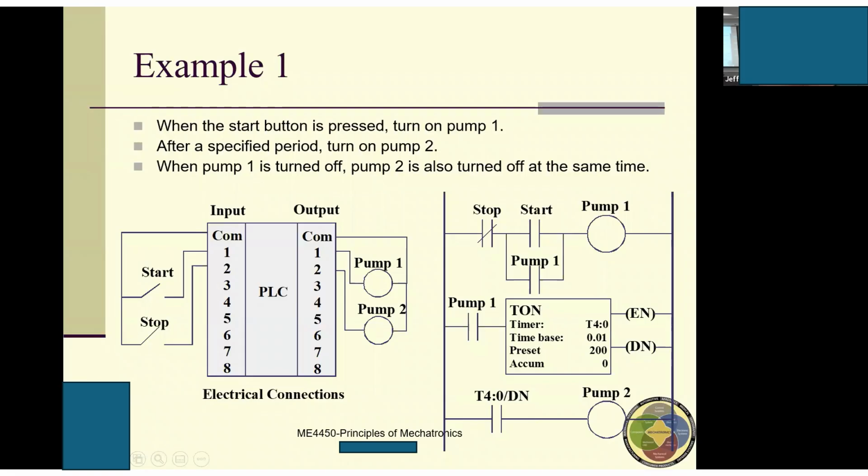Right? When we use timers and counters, the done bit will be used very, very often. And we use the done bit to control some bit or bits. Questions? Comments? Okay, so this is using TON, which is triggered by the false to true transition.